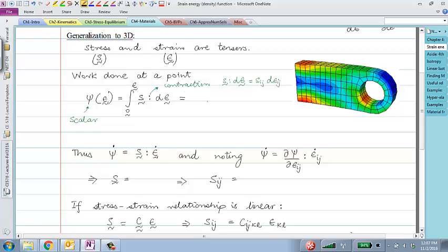If we think of the deformation process as a function of time, I can write that as stress double dot with the rate of change of strain. That's what the dot means. So it's d epsilon dt, and I'll have dt out here, integral over the deformation process from 0 to t. And this quantity here is called stress power.